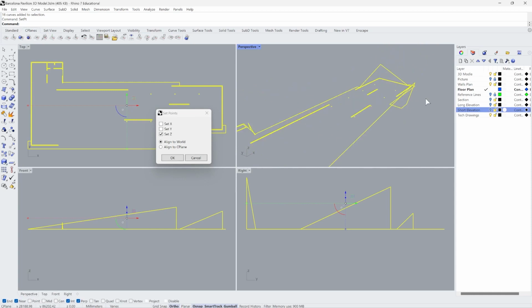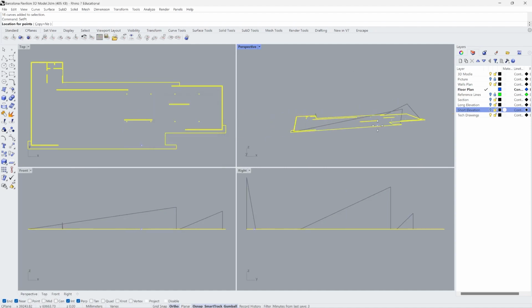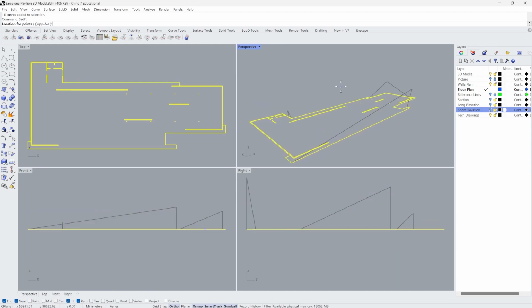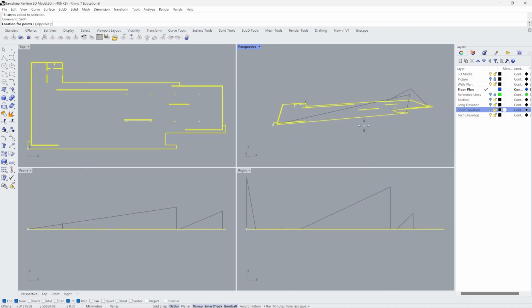So in our situation, we know that our points have been moved in the z direction, up and down. So what we need to fix is the z direction. We untick everything else except that, press OK, and you can see it gives us a little preview of how our drawing will look. It's almost trying to flatten all the points into the same plane. And the only thing it's now asking us is to specify which plane we want to flatten it to.